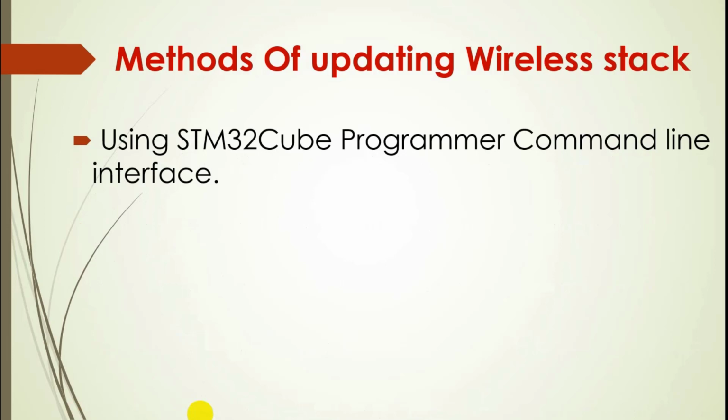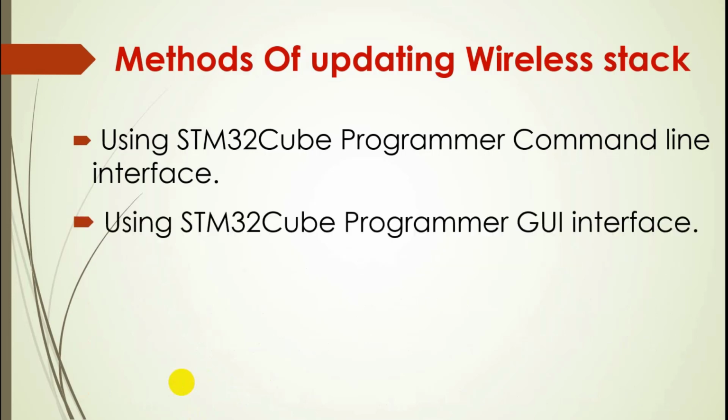I hope you know the STM32CubeProgrammer is a GUI by which you can update or flash STM32 MCUs. It comes with a GUI as well as a command line interface. The method we are talking about right now is using the command line interface. And we can also use the GUI to update the wireless stack of STM32WB.